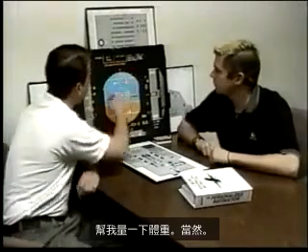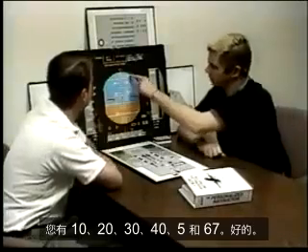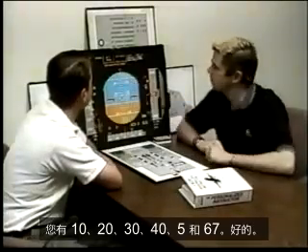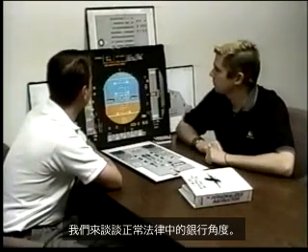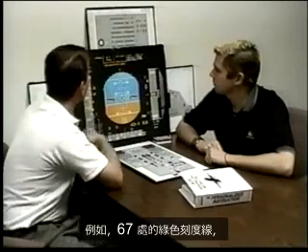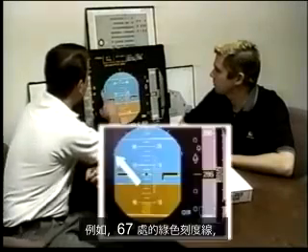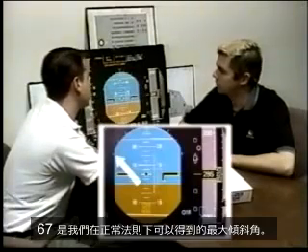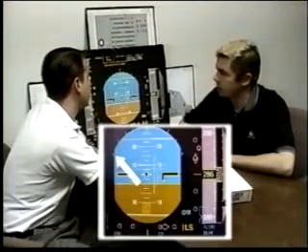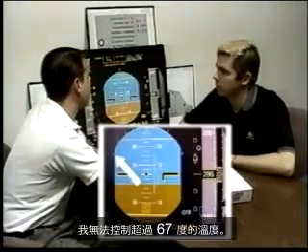Go through the scales for me. Sure, you've got 10, 20, 30, 45, and 67. Okay, let's talk about the bank angle in normal law. For example, the green tick mark sitting at 67. What does that mean to you? 67 is the max bank angle we can get in normal law. I cannot command any greater than 67 degrees.